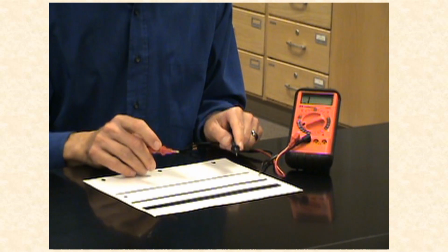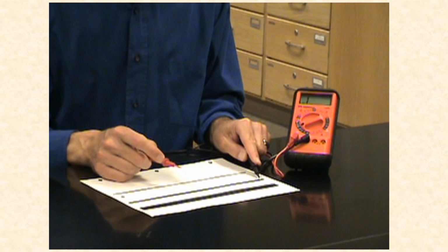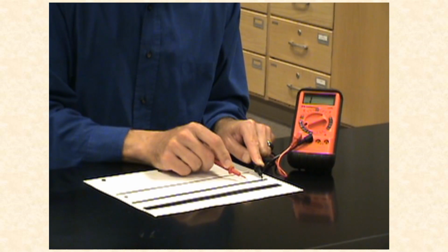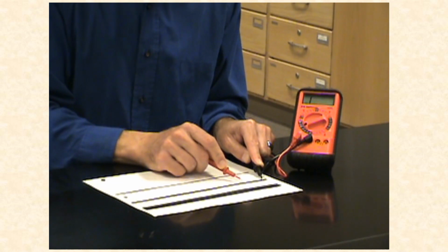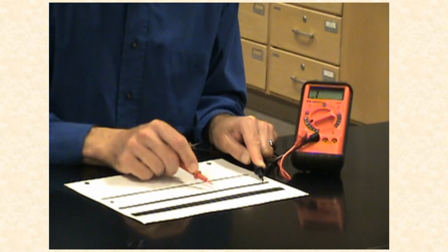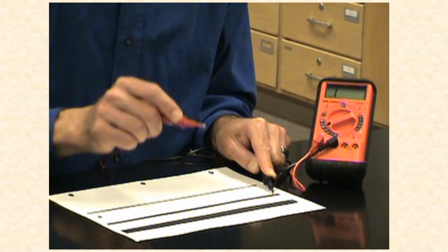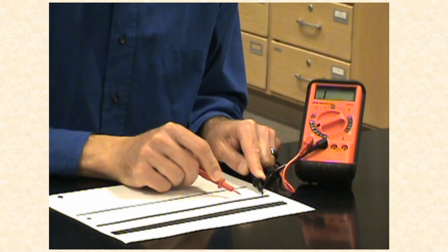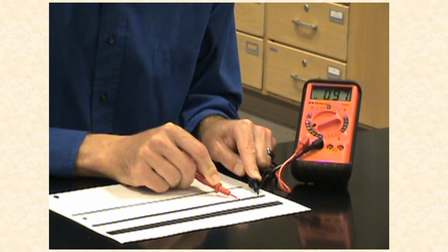So what we're going to do here is we're going to take a look at a piece of wire. I'll use this middle wire here, and I'm going to put the black lead of my ohm meter at one end, and I'm going to put the red lead at some distance away from the black lead, and I'll gradually increase that. So we'll measure the resistance across increasingly bigger segments of wire, and we'll see what happens to the resistance. So when I put my red lead a couple centimeters away, we get a resistance here of about 75 ohms.